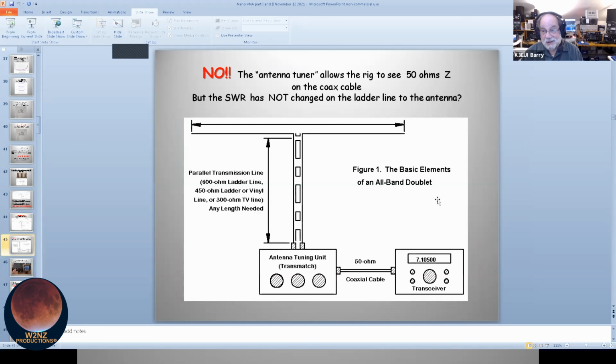Although if it's not at the resonant frequency and you're feeding it with coax and you have an SWR of 4:1, you may plug that into your transmitter and it might balk. I see some smiles because 80-meter operators know this. Why 80? It's always 80 meters. It's always the fisherman from Gloucester. And I fished out of Gloucester in the summer of my sophomore year, so I understand Gloucester fishermen, at least back in the 1960s. So no, the antenna doesn't have to be resonant.